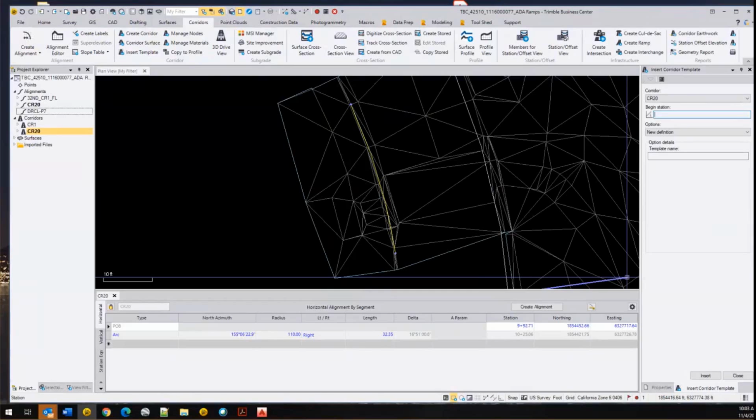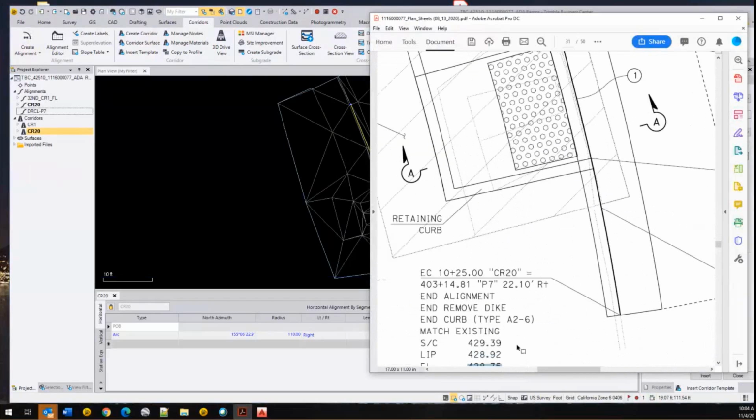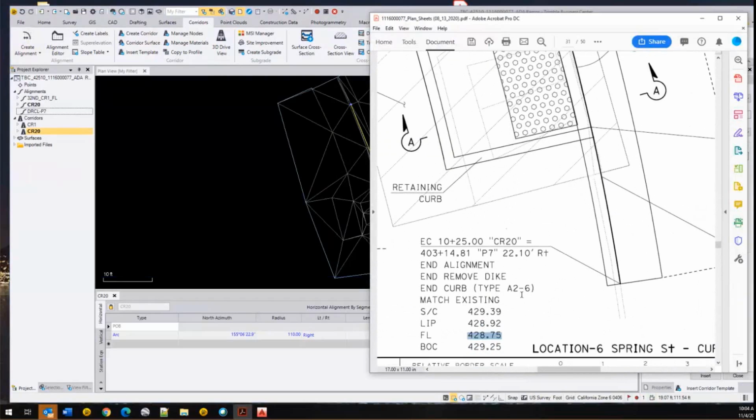And a lot of times we may not want it to go past a certain point. So one of the first things I do is give it a cutoff where I absolutely do not want it to work any further. In this case, it really isn't necessary, but I want to demonstrate what I consider best practices, and that is to create a cutoff template immediately after the last work you do.